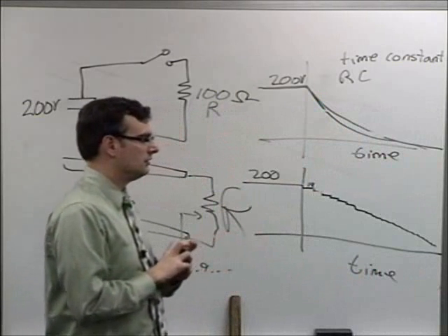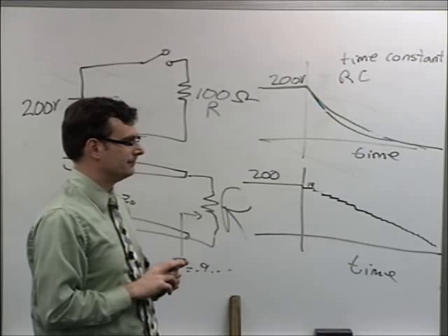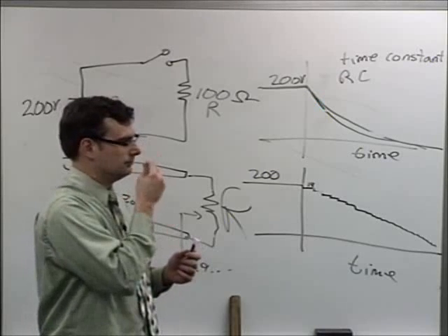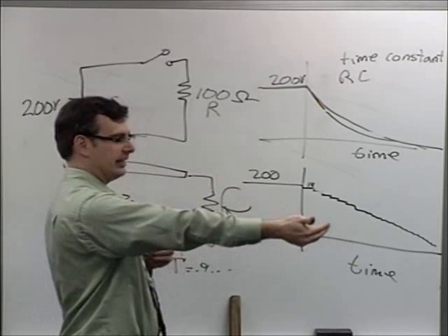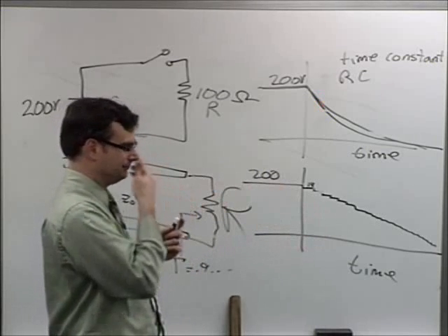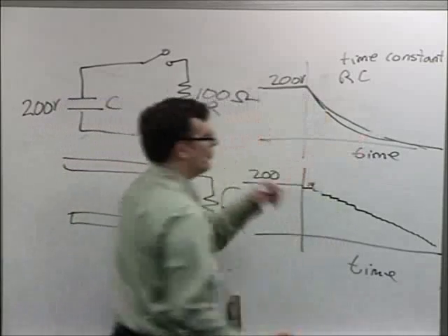how is it that it's starting at 200 and then 100 is getting wiped out going back, so you see 100 at the load end. But how is it specifically 100 going back when the reflection coefficient? How is it that 100 volts go back on that line? Okay, so a good thing to do now, let me just repeat that one step, but now let's use our equivalent circuit model